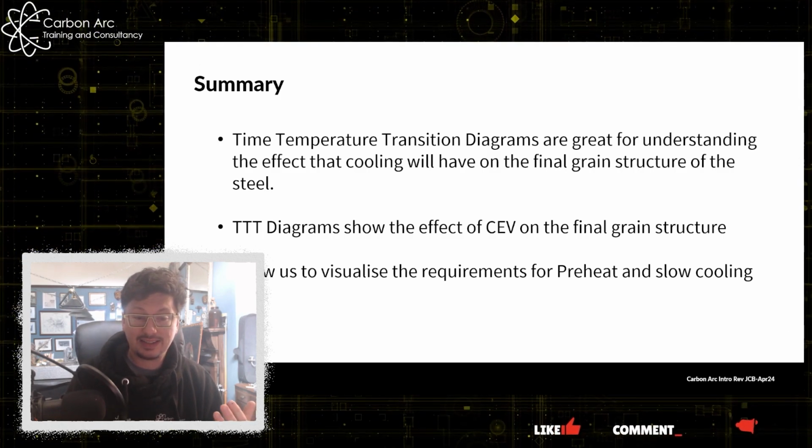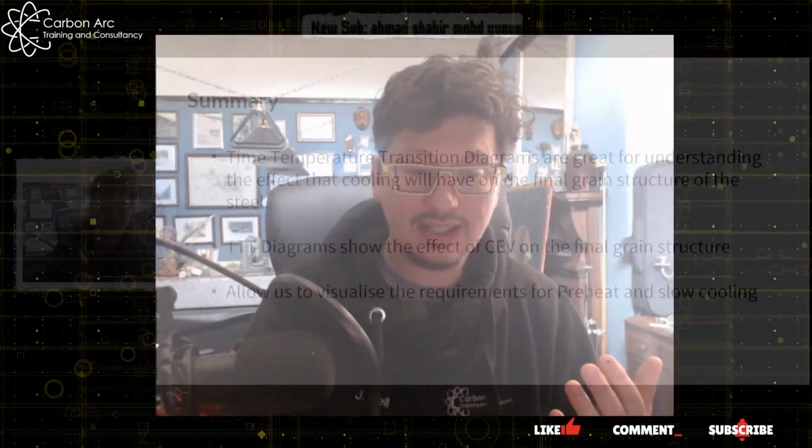Well, that's it really. It's a fairly straightforward body, but if you can remember the effect of that and visualize it, then you're going to be able to answer a lot of questions in multi-choices, especially around hydrogen-induced cold cracking, in hardenability and weldability within your exams.